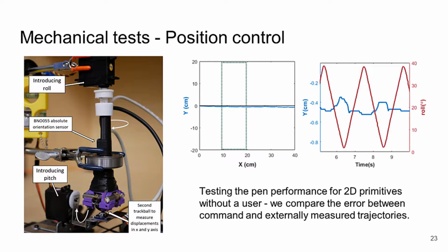The result shows that the system responds to rapid yaw changes at 0.5 Hz, 35 degrees peak-to-peak angle over 22 seconds, mimicking significant wrist rotation. When the user rotates his or her hand, the controller needs to compensate for the twist movement of the stylus to make it stick to the flat X trajectory as much as possible.